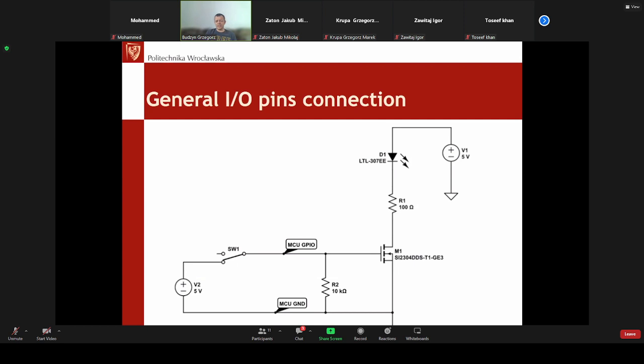Because the switch off will be faster, the charge will not be kept at the gate, but will be discharged by this resistor. So the switch off time will be faster. Especially today, when we have transistors with very high gate impedance, this resistor makes the difference.